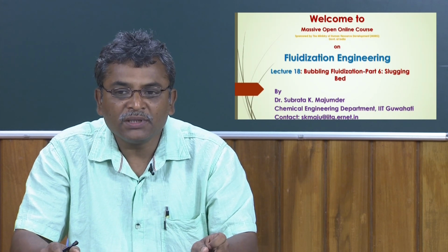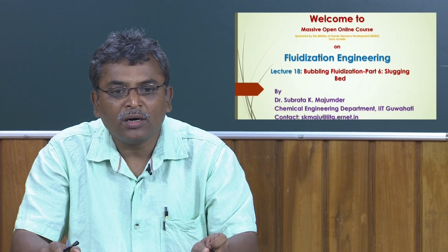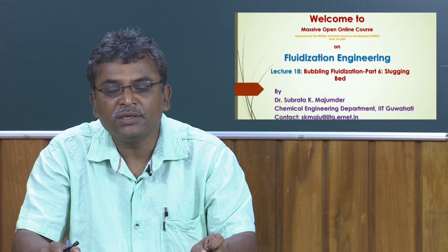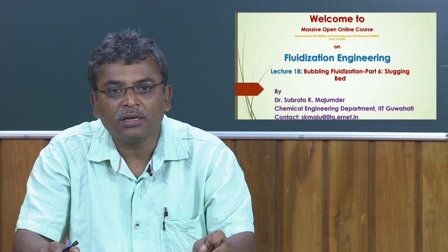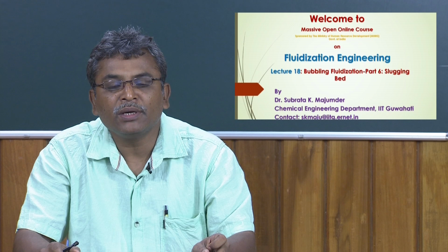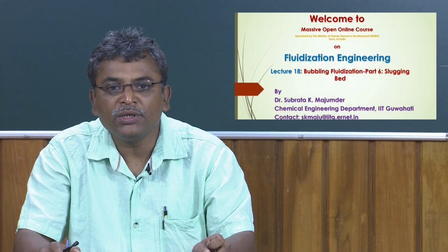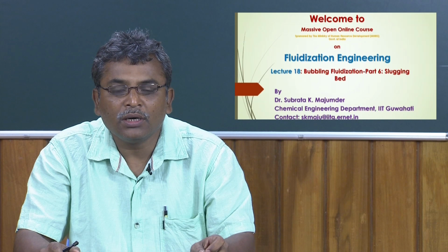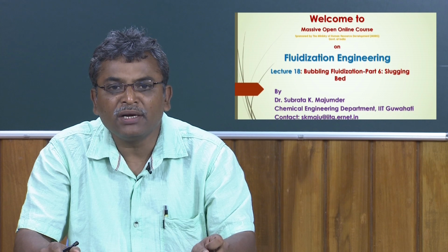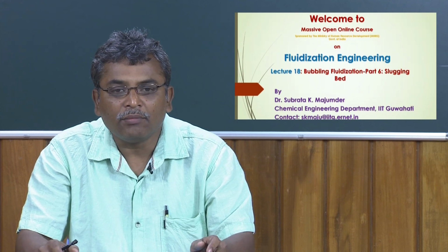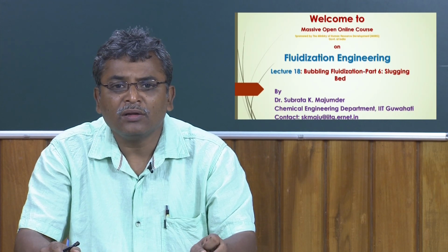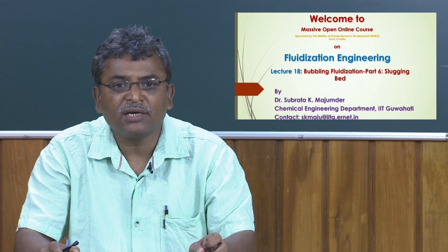We also discussed the different phenomena based on the concentration of solids, particle size, and particle movement, and what the particle movement will be when bubbles rise slowly or move very fast. These solid movement characteristics govern the mass transfer and heat transfer phenomena.